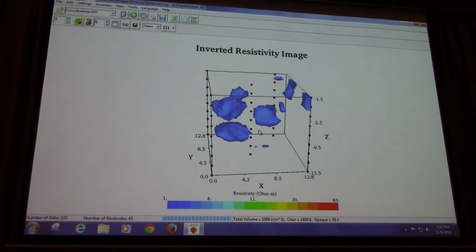And the problem is that DNAPL doesn't flow like a plume like we classically thought. What happens is that they'll put wells here, which they pump, and they bring it up to a piece of machinery that refines it, and it pumps the clean water back down and it washes the system through. But the problem is that if it's not flowing in the aquifer correctly, then you're never going to capture it all.